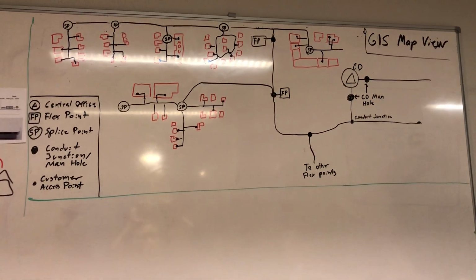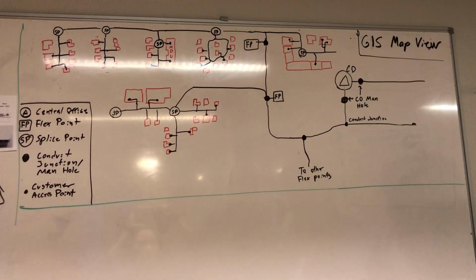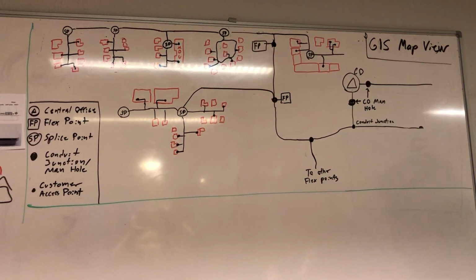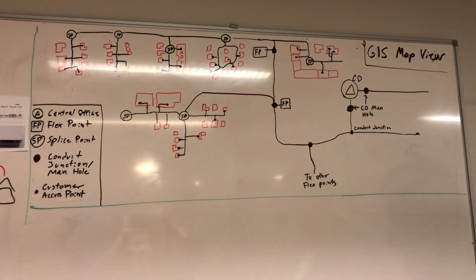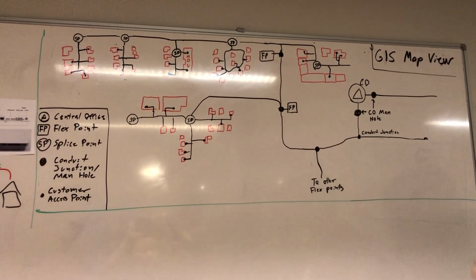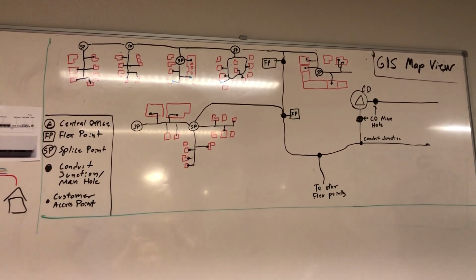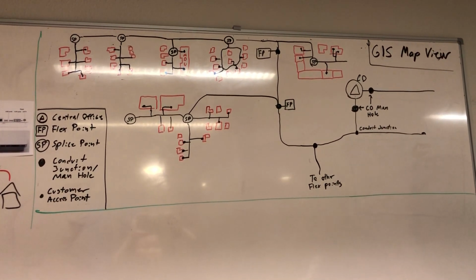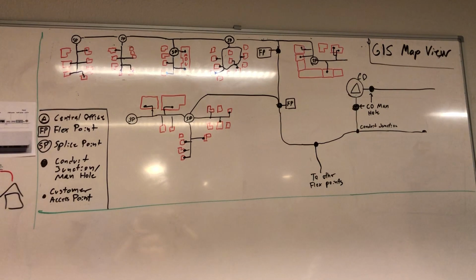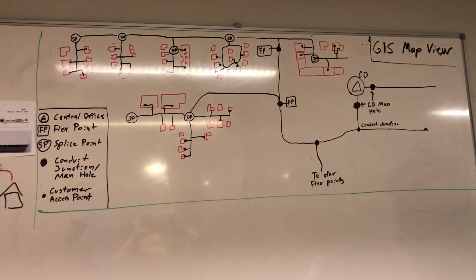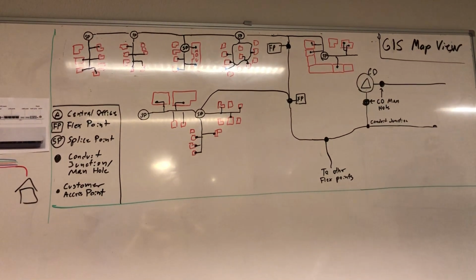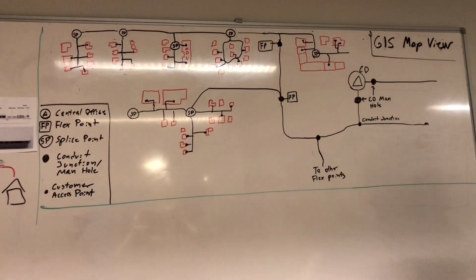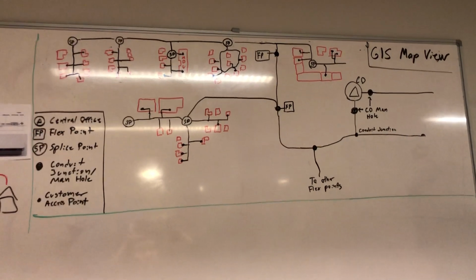Why do they have to blow? They have to blow the cable because there's the pipe. They dig down the pipe first, right? And then after they have done that, they will blow all the cable through the system. And also if something happens, someone digs over a pipe or something, they might be able to pull out the old cable and blow a new one. So they blow the cable when they roll out the different areas. They don't start by putting cable in the ground. Cables are quite expensive, so they only put the conduit in.